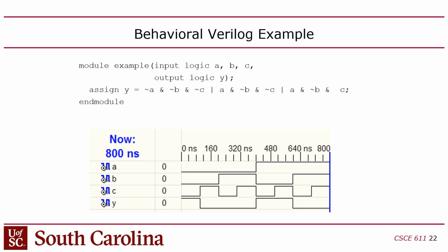The way it's shown here, it doesn't make any sense what those values are. But what they're trying to show is that these values will be updated according to where the cursor is. I don't know where the cursor is here. But wherever the cursor is, the values at that point are 0, 0, 0, 0, right? Does it make sense? So all of your testing is going to be in this form, unless you automate this. You can automate this with a test bench where you don't have to look at Y. You can have another Verilog module check that for you. But when you're debugging your code, you're usually looking at waveforms like this.